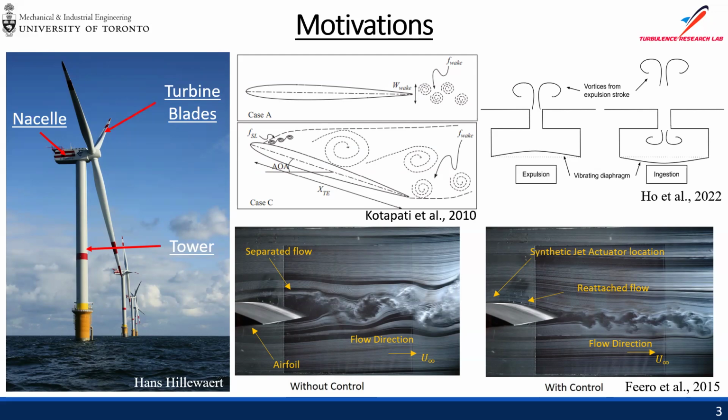On an airfoil, without the control, you can see the wake, the black voided regions, which basically separate the flow, and this is a fully stalled airfoil. The wake size is also pretty tall and unsteady, as indicated by the red arrow. With adequate control, we first suppress the flow separation, and the wake behind the airfoil is also significantly reduced, especially the height.